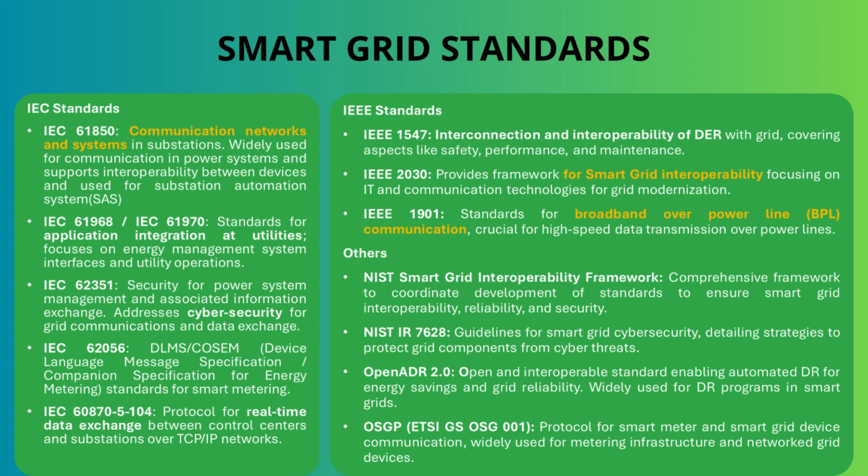IEC 62351 is vital. It focuses specifically on cybersecurity for all this power system communication. IEC 60870-5-104 is a widely used protocol for SCADA systems, real-time data exchange between control centers and remote sites like substations. What about IEEE standards?